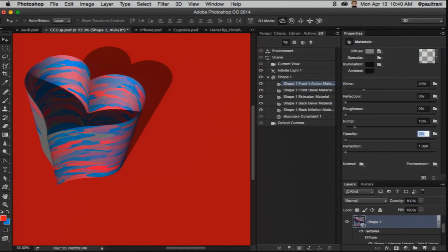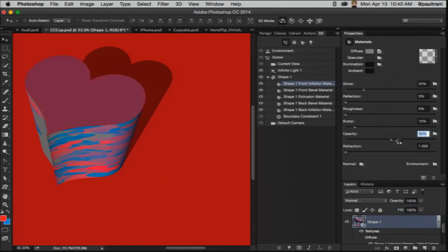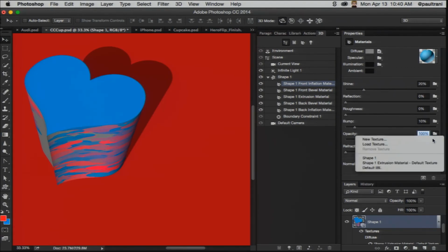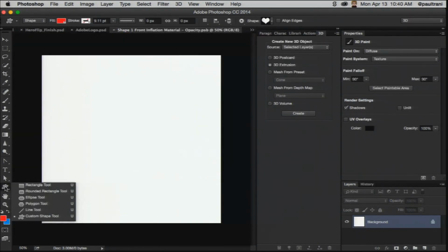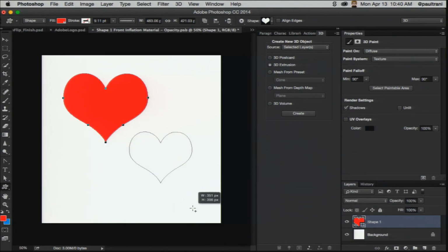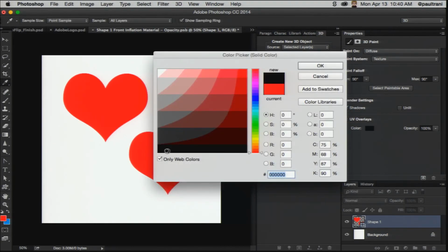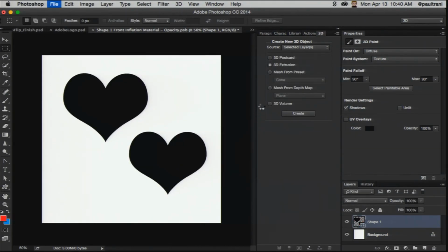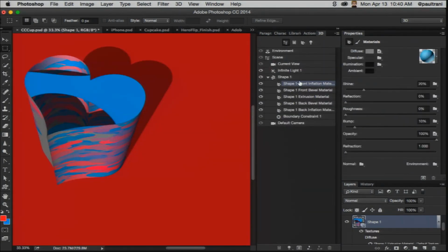That's what I've done. I could, even if I wanted to be more specific, create a new texture there. And if I edit this texture and I start painting in black, whatever's black is going to be the mask. Whatever's black is going to punch a hole in it. So right in here, if I wanted to have maybe two holes for two flowers as part of this vase, I can do that. Saving that, let's bring it back. Hold on one second. Yeah, it basically did that. It's a little funky. It's a little off in size, but that's what I've done, is I've just applied that transparency, that texture to that top part.